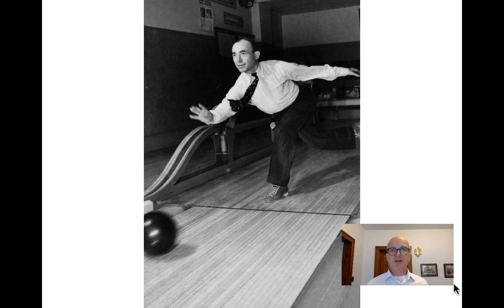Structural engineers are interested in putting the cross-sectional area of a beam as far from the neutral axis as they can. And you can think of what those flanges do, right? The resisting moment that they impart to the beam is analogous to the inertia of a professional bowling ball, one that's not only heavy, but that has most of its weight on the exterior. Therefore, hard to get rolling, but also very hard to stop.